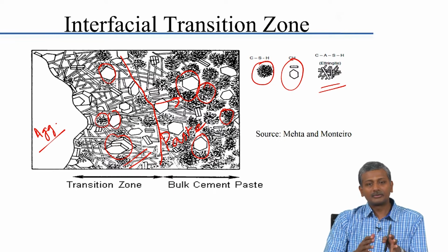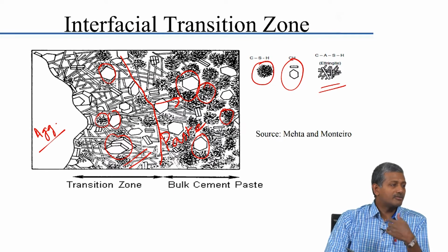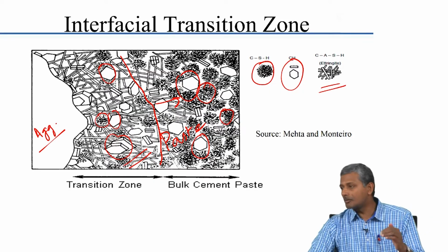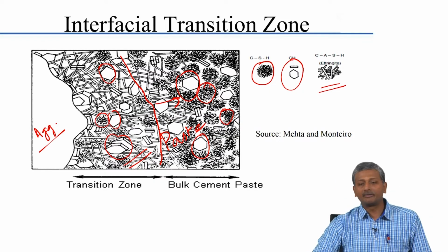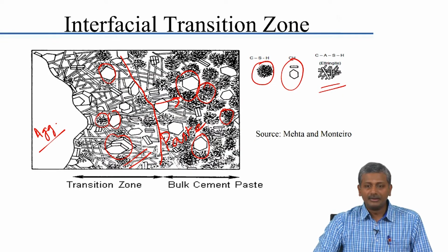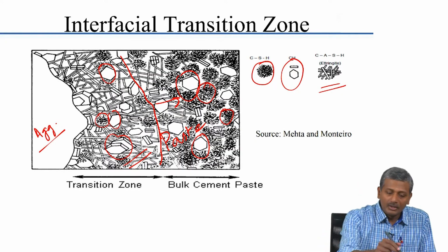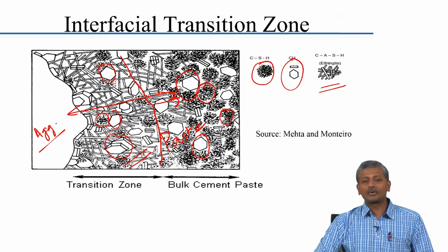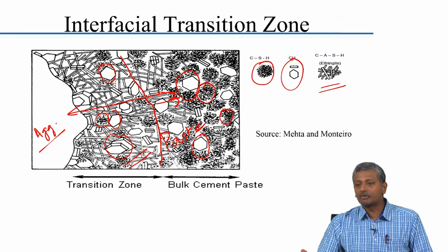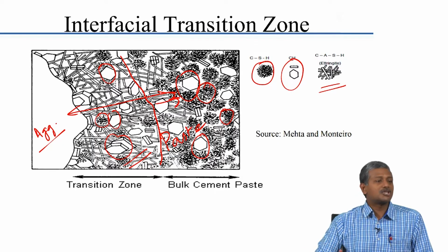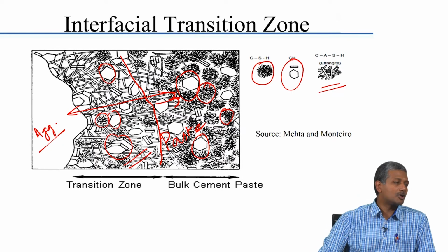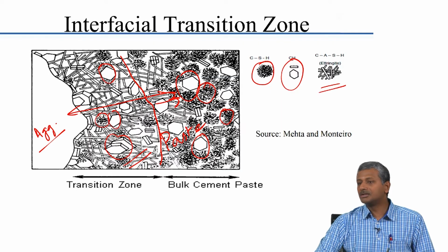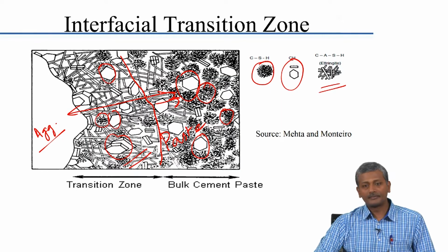Okay. So, because of that you have a change in behavior from low strength to high strength concrete, from a ductile to a brittle behavior. So, high strength concrete you all know is brittle, and that brittleness is caused because you are more or less homogeneous. That means your ITZ is no longer much different from the paste, and the paste has sufficiently high strength that it is comparable to the aggregate. So, you have now a homogeneous mixture which leads to a brittle failure.